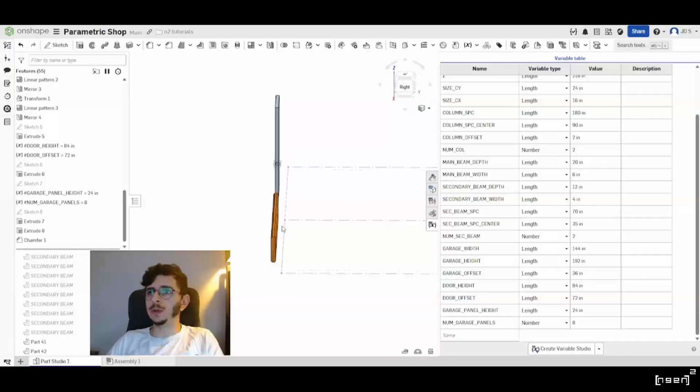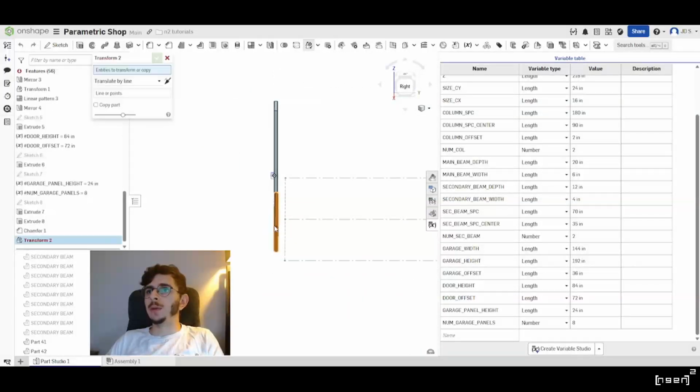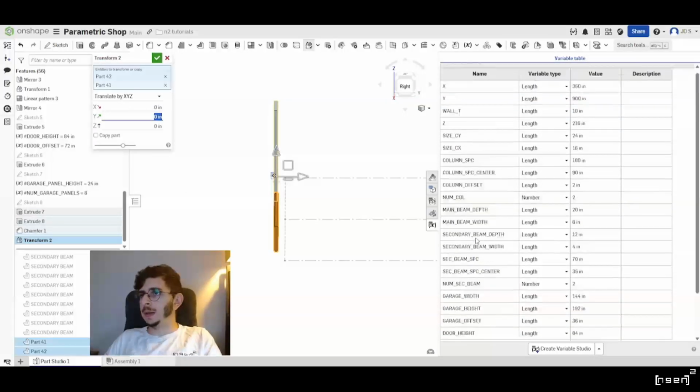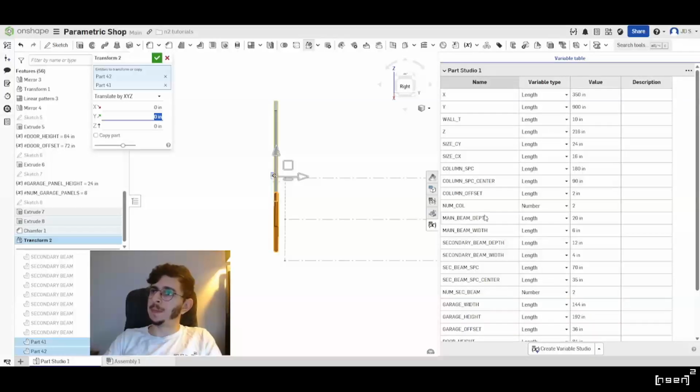And the door, we can leave it as is. Both of these, we will offset them inside just for visual effect by the wall. Let's do wall thickness divided by 1 inch. So this will just always guarantee a 1 inch offset if it's working the way that I thought it would.